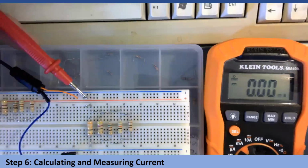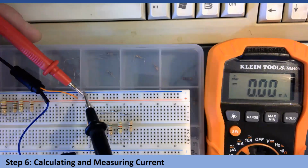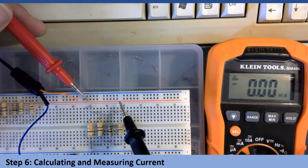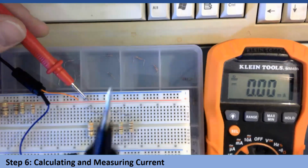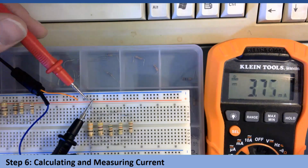So now the power is coming from my power supply through the rail to my red lead. There is no connection between the power rail and my workspace. So now, in order to complete the circuit, I have to use the meter itself. So I'm going to stick the black into it, and I'm getting 3.8 milliamps.